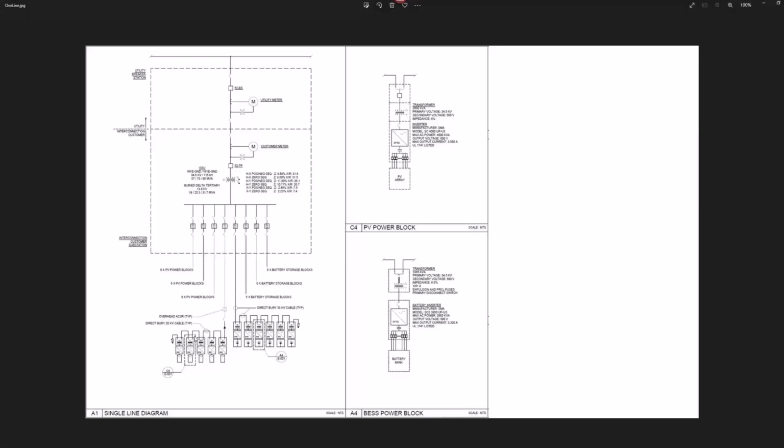So that's your step-up transformer or pad mount transformer to collect your inverters together to the 34.5 kV. All those things should be explicitly modeled in EasyPower to evaluate the power plant harmonic performance, right? So this is the one-line we need to consider and collect first.